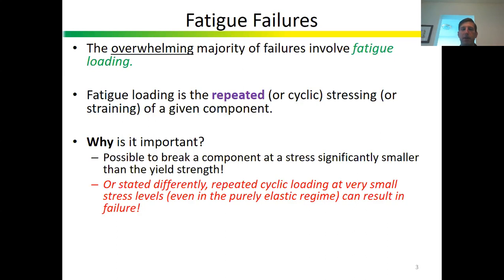That would imply that the stresses or the loads you're applying to the paper clip are very high. Alternatively, someone might unfold the paper clip and just twang it or bend it ever so slightly back and forth in their hands. And maybe you can do that for several minutes or even several hours if the load is very low, but the paper clip will probably eventually fail.